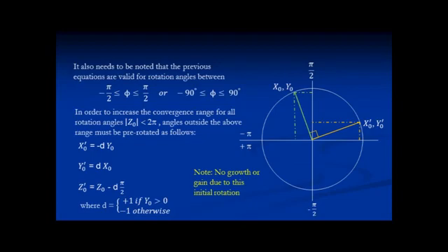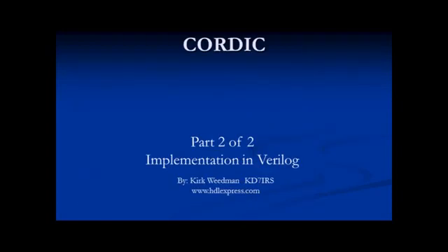Now let's look at an actual Verilog code implementation of this quartic algorithm. It can be written very concisely. This is a basic quartic function as described in part 1 of this presentation. Improvements could be made, such as rounding the outputs of each stage to reduce error and other things, but it's still quite accurate. After looking at the Verilog code, I'll run a simulation that will display sine and cosine outputs by feeding this quartic the proper inputs.